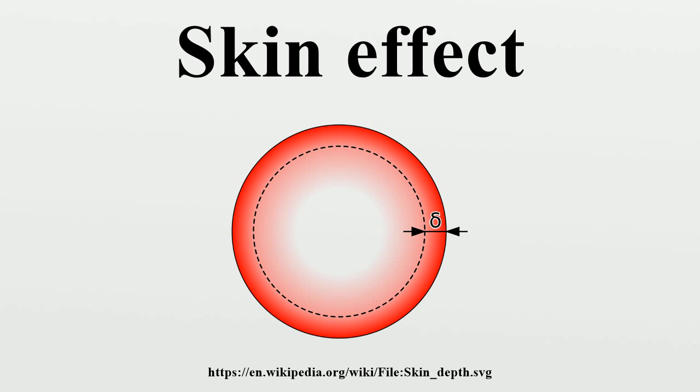Although it has a lower conductivity than copper and silver, gold plating is also used, because unlike copper and silver, it does not corrode. A thin corroded layer of copper or silver would have a low conductivity, and so would cause large power losses as the majority of the current would still flow through this layer.